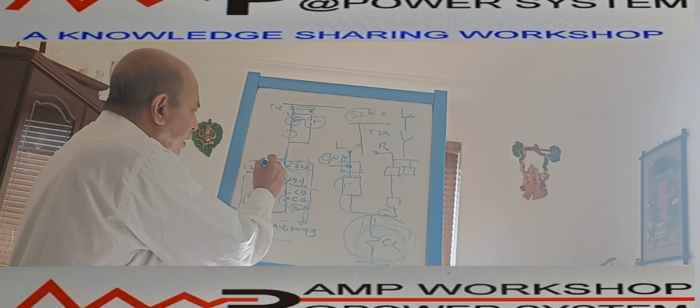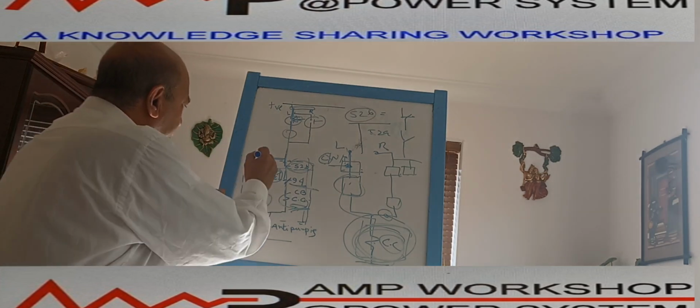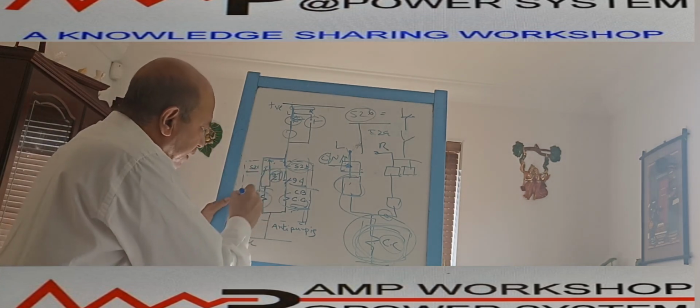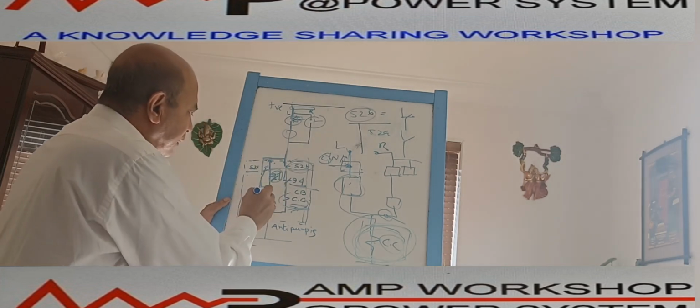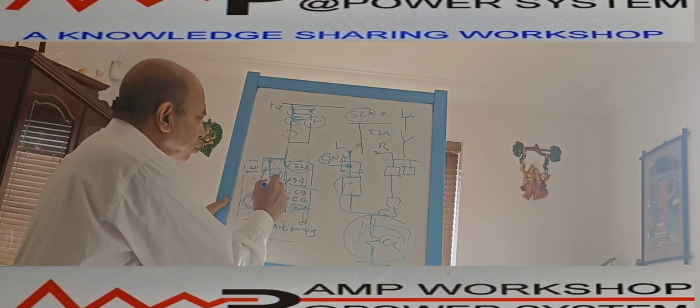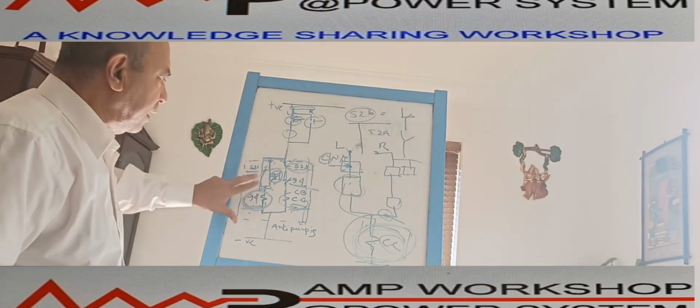And this relay is already energized through this contact, but the moment the anti-pumping relay picked up, immediately it is also NC. So when the breaker is closed, immediately what is happening? The anti-pumping relay is picked up. As the breaker is already closed, this is closed, so the anti-pumping relay is getting power. The anti-pumping relay picks up, and then this NO contact becomes NC. So it is also picked up. That means the anti-pumping relay is getting power supply through this position, through the breaker auxiliary contact as well as the anti-pumping relay auxiliary contact. Once the breaker is closed, this is the scenario.